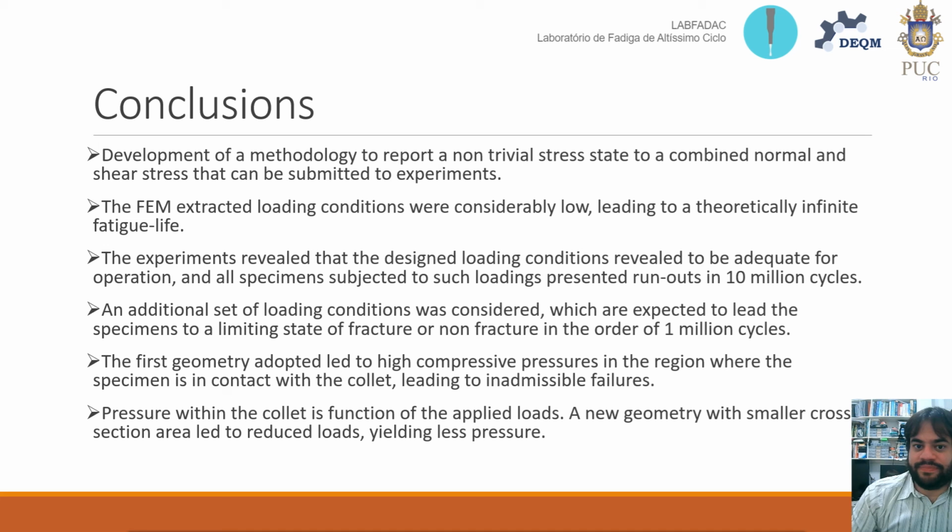Runouts were no surprise. An additional set of loading conditions was considered. These loading conditions are expected to lead the material to a critical condition on the verge of failure. Unfortunately, experimental problems arose which imposed updating the specimen's geometry to reduce the grip's pressure, avoiding the out-of-place failures.